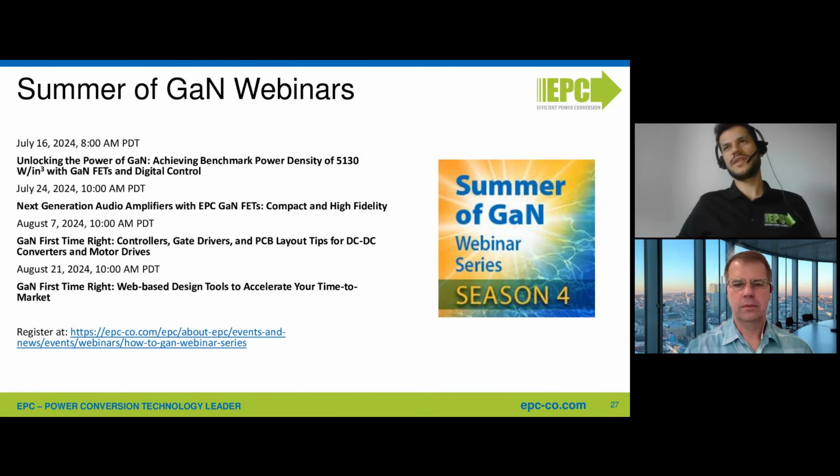It's more evident in motors that have smaller electrical constants. So motors with low inductance benefit more from the characteristics of gallium nitride inverters. Yeah, that makes a lot of sense. So it's selecting the right motor or the right application for applying GaN where it really is going to benefit.